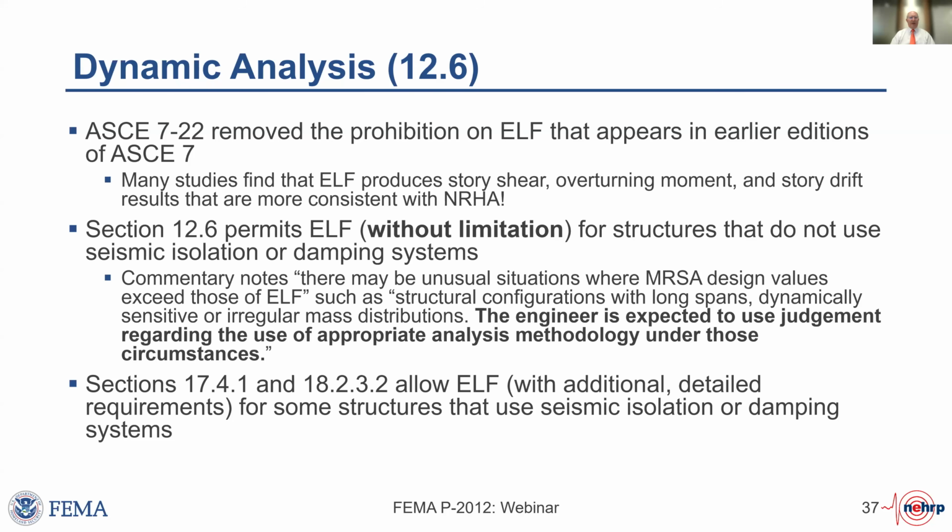So then for dynamic analysis, I mentioned before that the prohibition on ELF was removed because we find that more conservative ELF analysis actually produces results that are more consistent with the true dynamic inelastic response than the modal method would suggest.